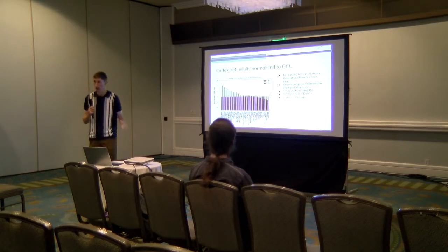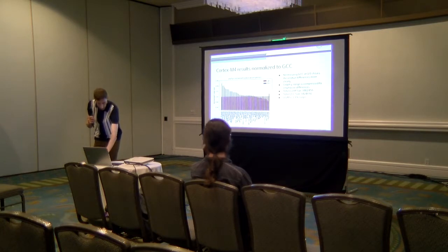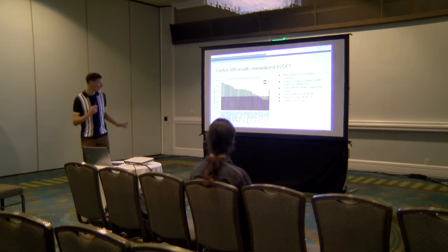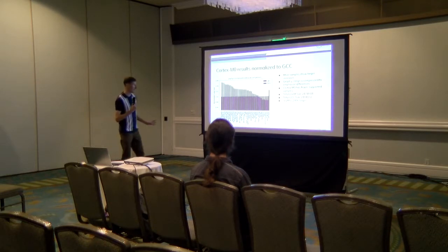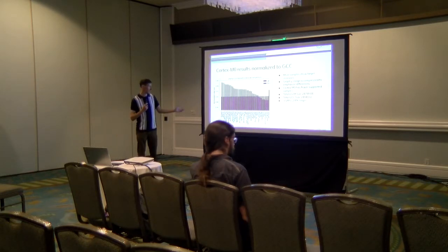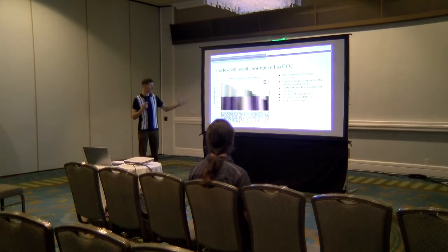So yeah, we did Cortex-M4 and Cortex-M0, Cortex-M4 with Thumb 2, Cortex-M0 with Thumb 1. So there are definitely code generation challenges at Thumb 1 only. For Cortex-M0, we'll notice that GCC does better still here. A lot more of the peak differences are very much the same, but more applications, so larger code differences there.